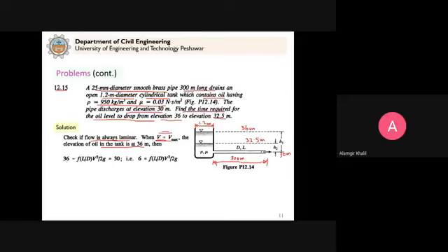So now we consider this equation: Z of 36 meter minus the major head loss will be equal to 30 meter here. We ignore other terms. Clear? Because we have oil flowing in laminar flow, the velocity head and other terms are negligible compared to the major head loss, since the length of the pipe is 300 meter, which is significant.